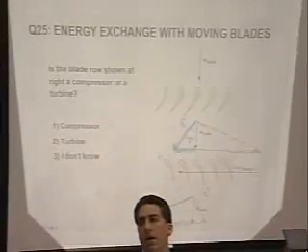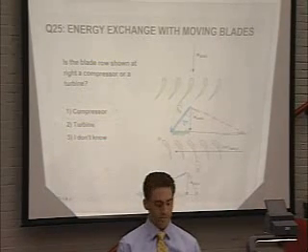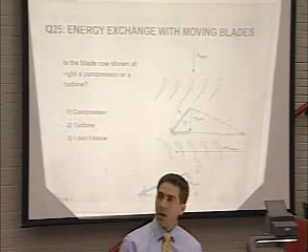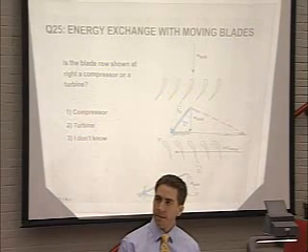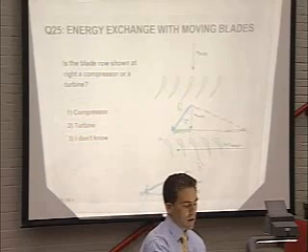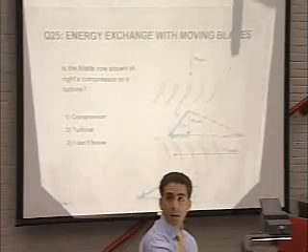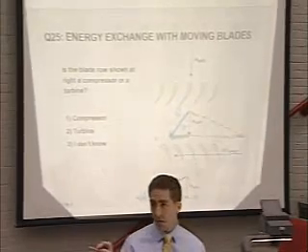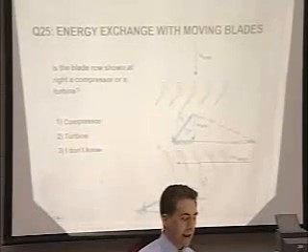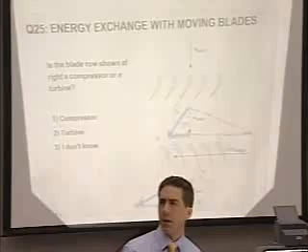Questions about that? Yes? Can you also look at that as the tangential components going that way, meaning the work is going downstream? Well, again, the point of these is that they take a flux, which is the axial component of the flow, of angular momentum and change it. And the angular momentum here is in the direction of rotor motion.